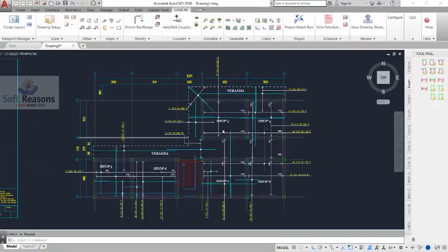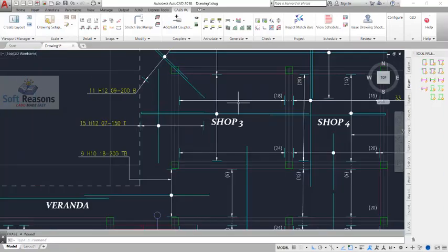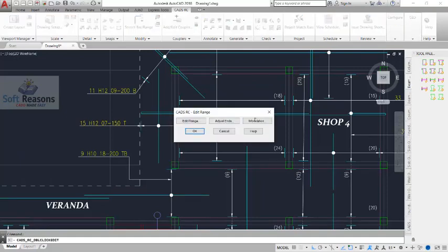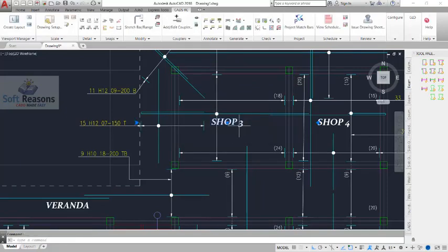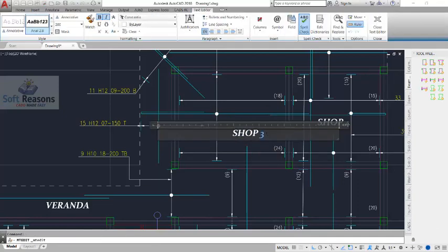Also, assign your slab thickness. So let's try to use this short text. Okay, so you can always double click on the short text, and then you change it to, just make it 150 millimeter thick, right? Just like this. Slab, all right. So click on it.